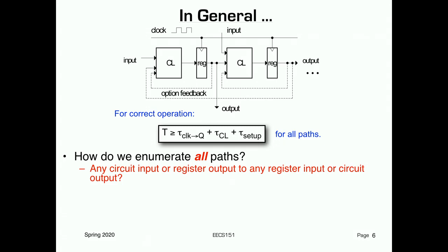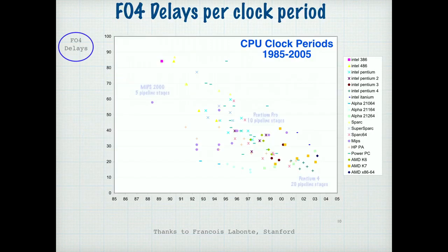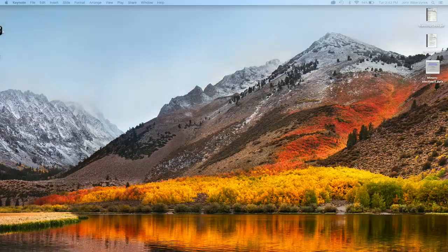So if the design is failing to meet the timing constraint, there won't be enough time for the signals to get to where they need to be. And that could be fixed either by slowing down the clock, allowing a longer clock period, or by shortening the delay paths. So that's timing optimization: shortening the delay path so we can increase the clock frequency. Let me skip some of this back to where we were last time.